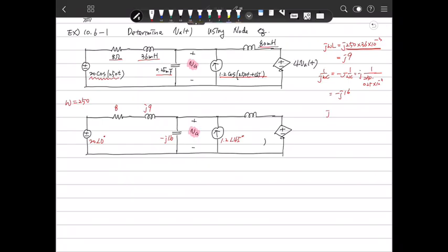And that is j omega L, because the inductance is 80 times 10 to the minus 3, with omega 250. So that will be j20. This is j20. Then we check the 4 VA phasor. We replace it, that is VA. The numbers are very simple.